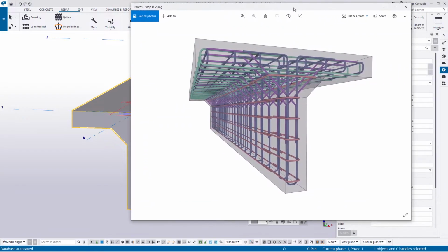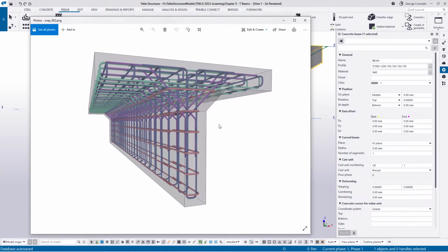I have done a run on this prior to generate this little T-beam screenshot for us, because I didn't have a proper reinforcement example at hand. So we're going to first focus on the outer reinforcement. It's the cyan bars that you see in the flange of the beam, spaced at 200. Then we're going to focus on the red ones, which is the outer layer of the web.